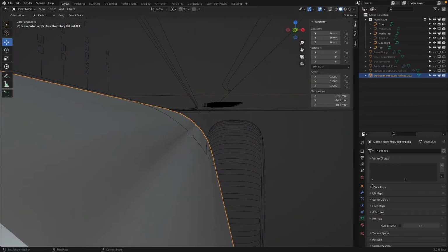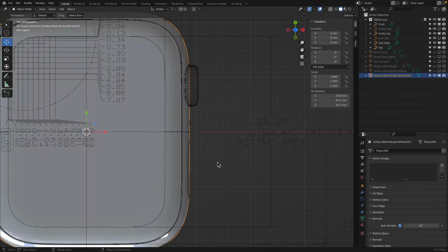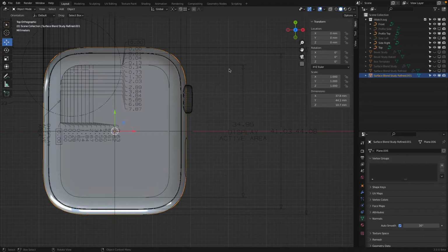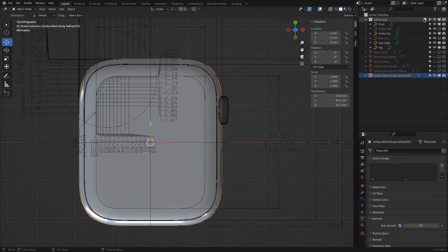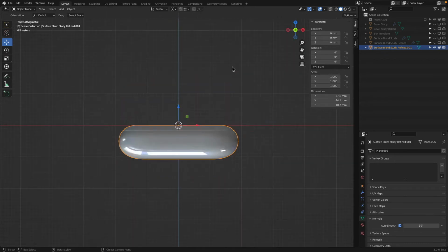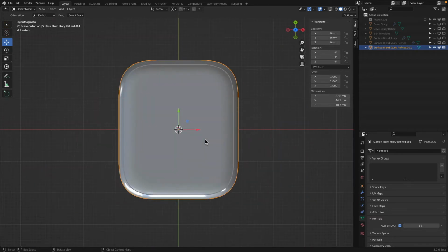Very good. Now this looks kind of like a soft groove. So we go to Object, Data, Normals, and Auto Smooth. Ta-da! So with this, we actually finished modeling the top body, and then we will do the cutouts and push button and then the crown.